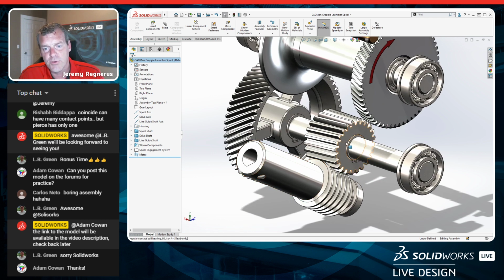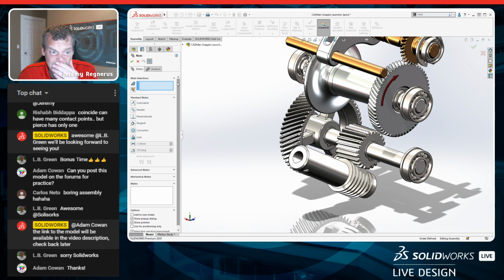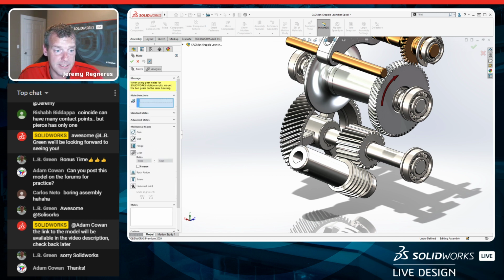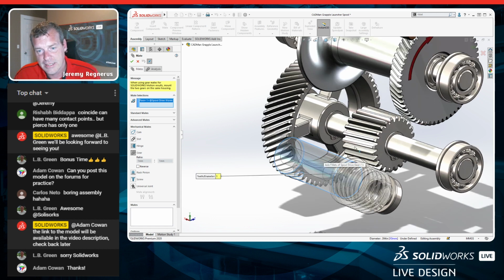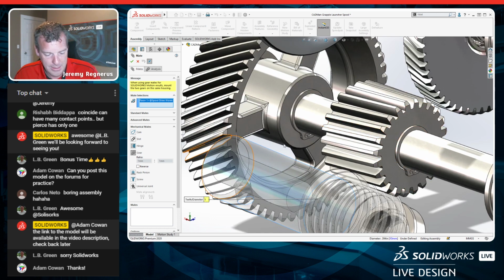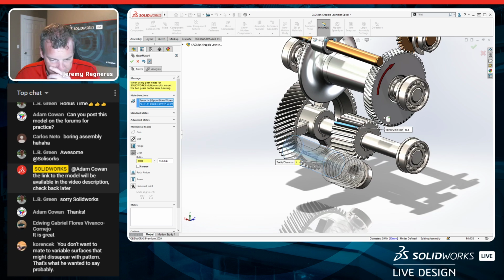And let's create a complicated gear mate between this worm gear and this spur gear right here. So we're going to go grab a mate. And we're going to go to mechanical mates, gear, and we're going to grab the driving worm gear. And worm gears are always kind of done at a ratio. The trick I just showed you really can't be done for a worm gear, so I want to show how to do this, I guess I'll call it, the old-fashioned way. And then we're going to grab one of these cylindrical surfaces here, and the ratio of this is 1 to 24.